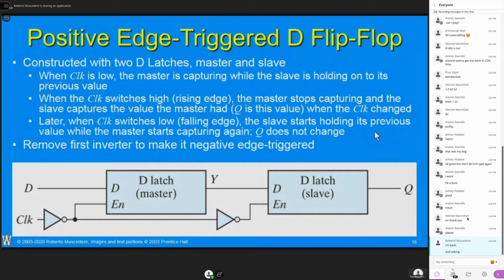But if you clocked it too slow, it would also fail because there were a lot of self-timed circuits in there to preserve register values, which weren't registers at all. They were some bizarre self-timed device that worked at a particular frequency, but nothing less. So we don't do design like that anymore where those things are that specific. If you build a design with D flip-flops, you can effectively set the clock to 0 and the circuit will stop. And the moment you turn the clock back on, it will work.